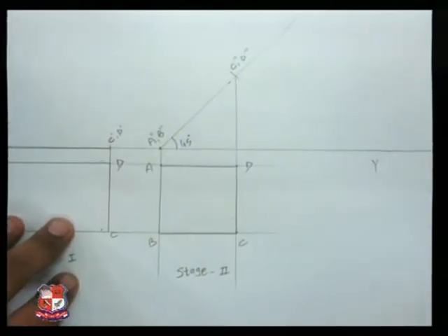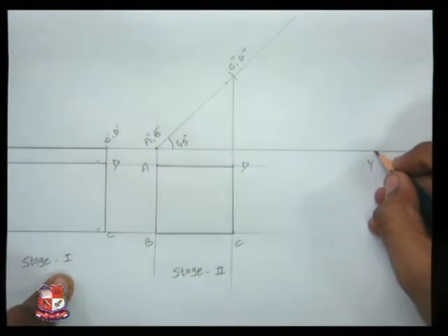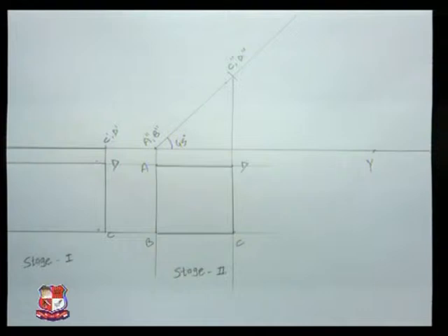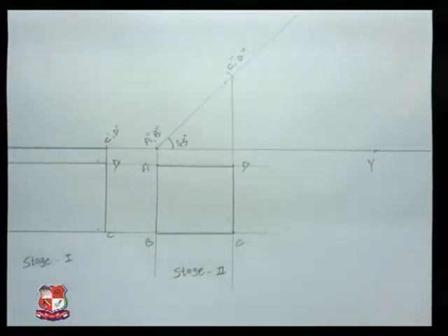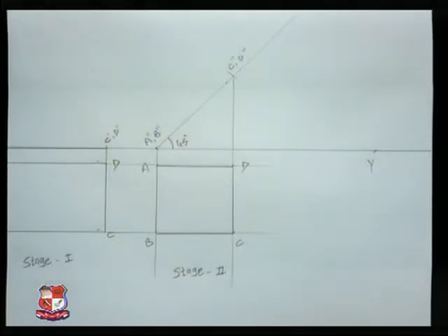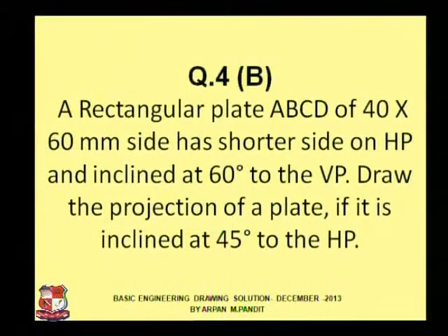Now, third and final stage, stage 3. In this, we are going to implement the VP angle as well. Look at the example, what VP angle has been given. VP angle has been given as 60 degrees, which means that on the lower side we need to draw a 60-degree reference line. How we can draw this? I will show you.